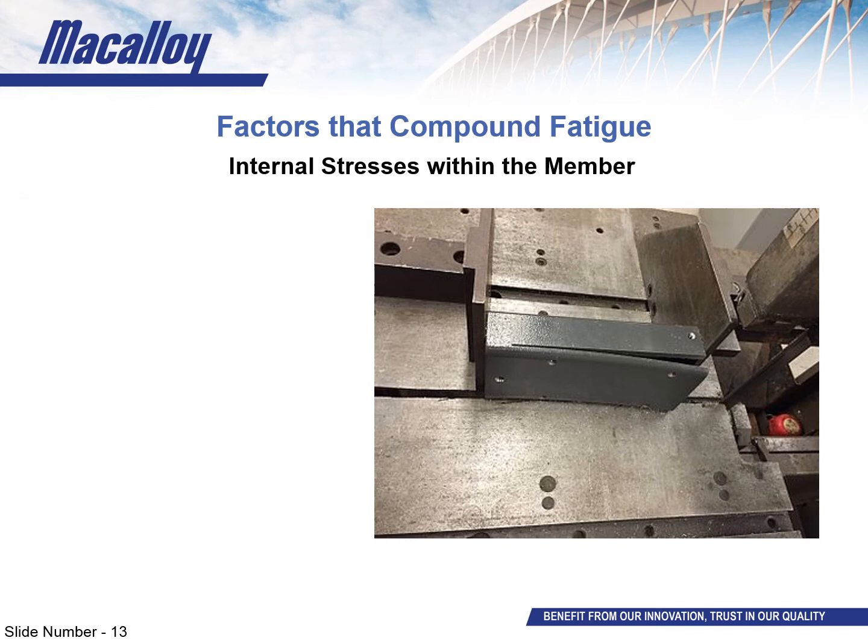You can see there an example of what residual stresses can actually do. The outside faces of that section cooled faster than the inner faces, and as a result they generated residual tensile stresses. These stresses were trying to bend the outside faces of the section away from its centre. However, the rest of the geometry was stopping that from happening. Once the material was cut though, as it was in the image shown, the internal geometry is no longer restricting this movement, and the residual stresses actually took over and deformed the material.